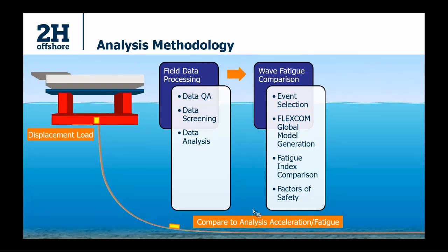For example, we don't use structural damping. We use strake CD of 2.0, for example. And we would find out the response at the bottom at the location of the TDZ logger, and we'd compare that with whatever we have measured from the actual TDZ logger. And we would then calibrate our parameters, the parameters that we think can be played upon or should be played upon, and we try to match the response better. We also develop some factors of safety in this study.